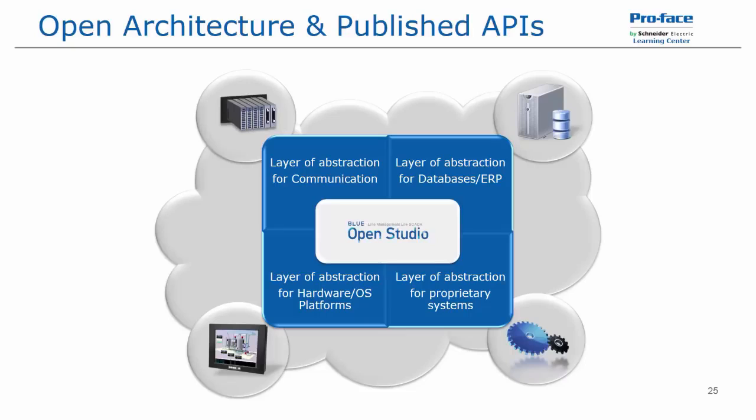Let's say that you were migrating from a PLC. Let's say it is an Allen Bradley ControlLogix, and you want to move to Schneider Modicon Modbus TCP. With some software, that would require you to add a driver, then change all of your I/O addresses, or go into the symbol variable list and change what I/O addresses those symbol variables are tied to, and then remove the old driver.